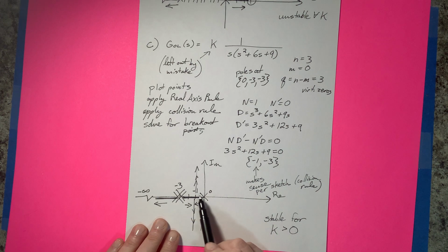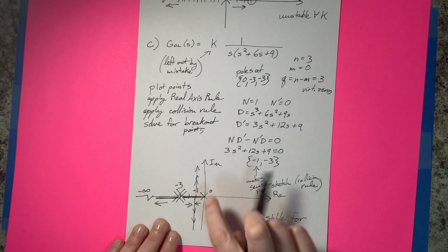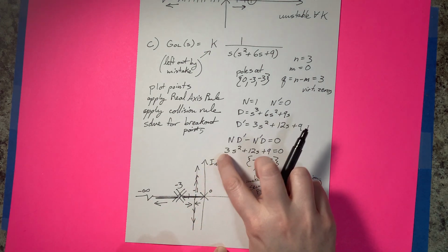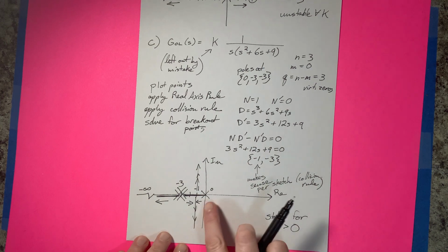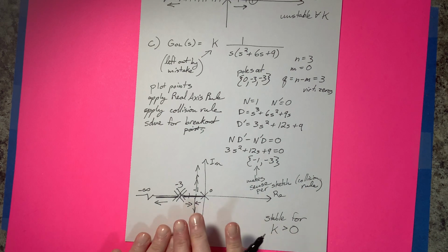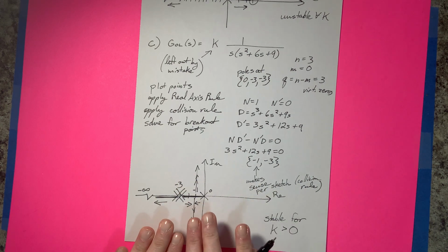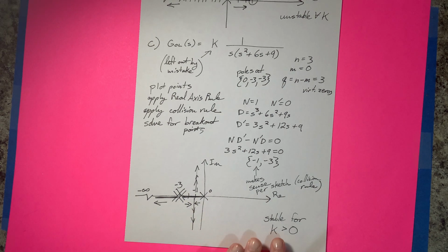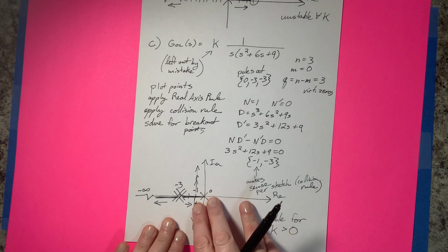If you completed this with the angle formula, of course, your movement will go out here into the right-hand plane at some point. So I'm answering with respect to what I would assume that you had thought about and drawn. It'll be stable for all k greater than 0 in that case.